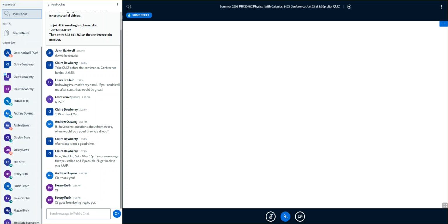Then they talk about a ball in free fall, and this is an extremely interesting equation. We will encounter it in fluid systems that have no laminar flow. It will be all ideal flow, which is called streamline. I particularly want to point out that the final velocity squared is a combination of the change in height. If y's height is 0, then the final velocity is the square root of 2gh. And we want to try to make either the initial or final position 0 anyway.